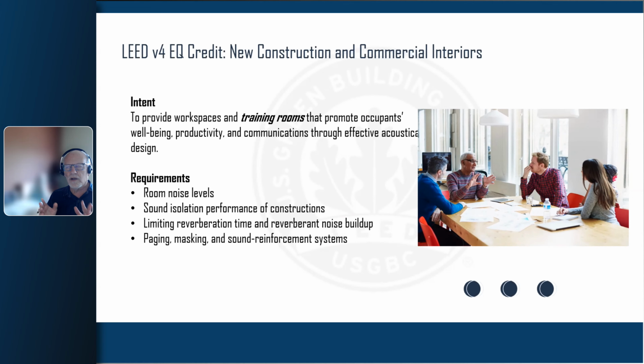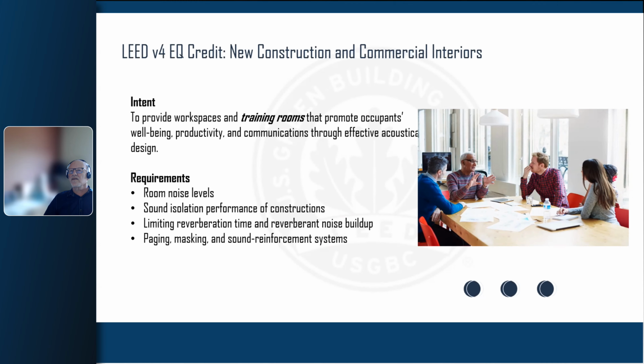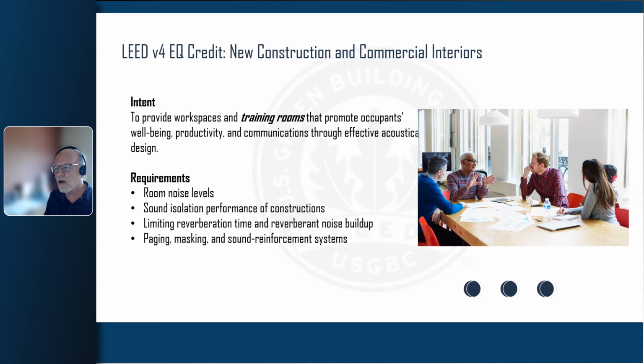Yes. Well, no. When you test to the ASTM E standards, the ones I referenced at the very beginning, it references a test regimen where the door has to be opened and closed, and then the test starts. So it does take the gaps into account if it's in conformance with that ASTM standard. If it's not, and it's an inoperable door panel that we've used for R&D purposes, then no gap is being allowed for. So the question about operable and inoperable comes into play, and you probably asked that question before I went through that.